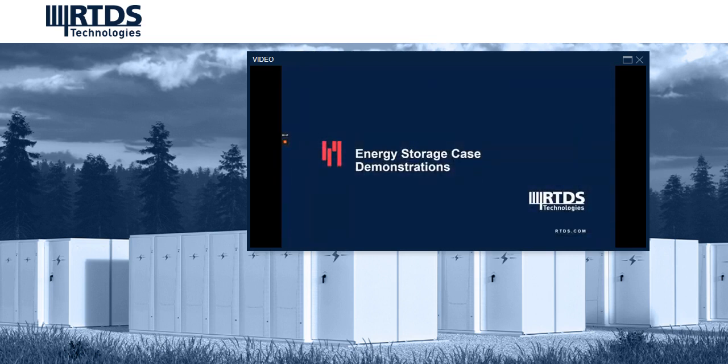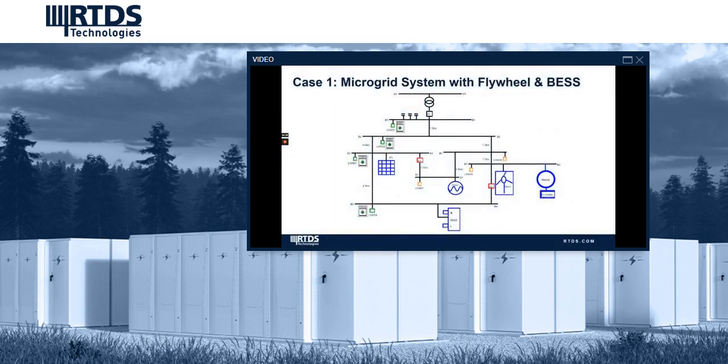In this next section, energy storage case demonstrations will be included with a brief discussion of the cases that will be described and demonstrated. The first case is a microgrid system that includes a battery, a flywheel, a wind, diesel generator, and PV. The microgrid can be operated in grid-connected and islanding mode. The microgrid can be resynchronized back to the grid by using several control systems, including a switch capacitor bank, to maintain the resynchronization voltage and phase angle and frequency within the specified limits for reconnection back to the grid.